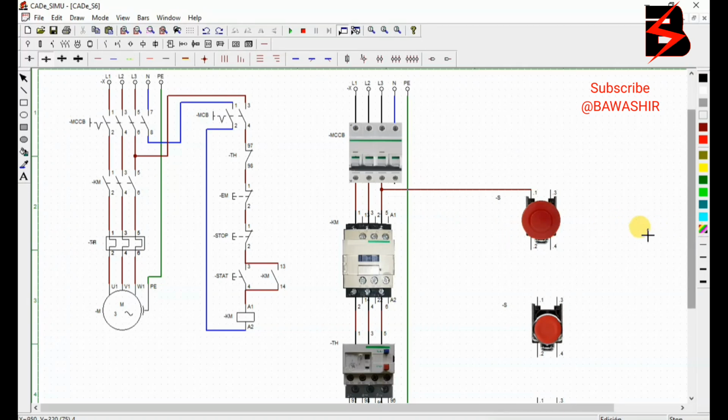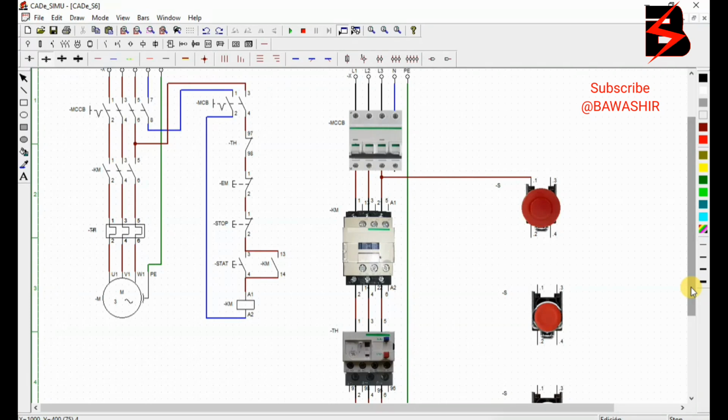Now there are some engineers, it doesn't matter what you consider first. Some from power first take through the overload, others first through the emergency, the one I'm doing, then the stop, then it is the neutral that they pass through the overload, provided the circuit can be broken when there is an error with the overload. We shall see during simulation.